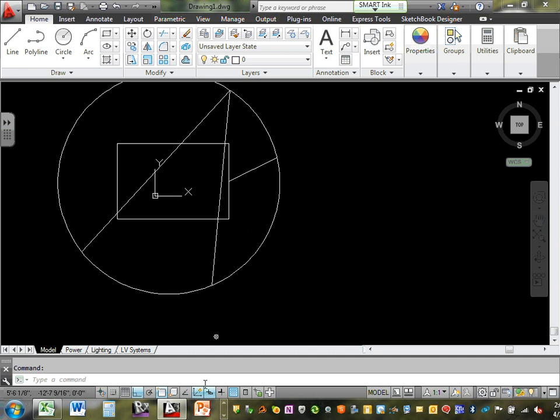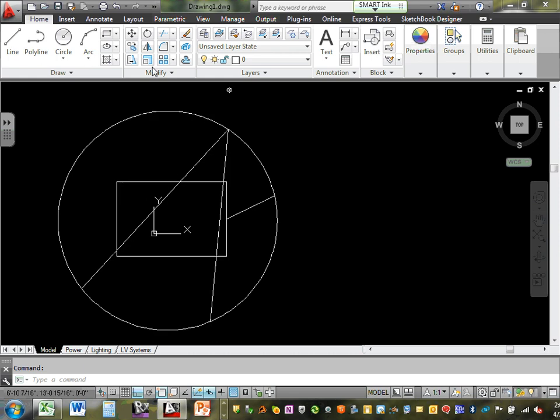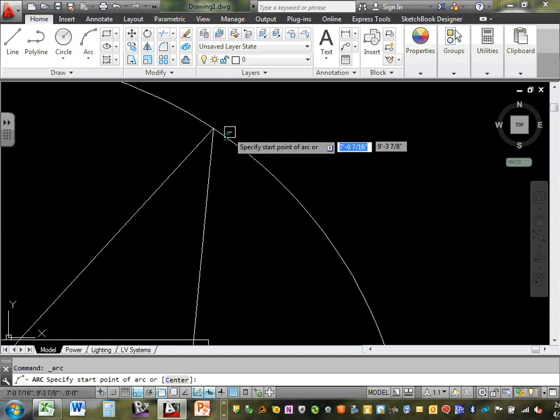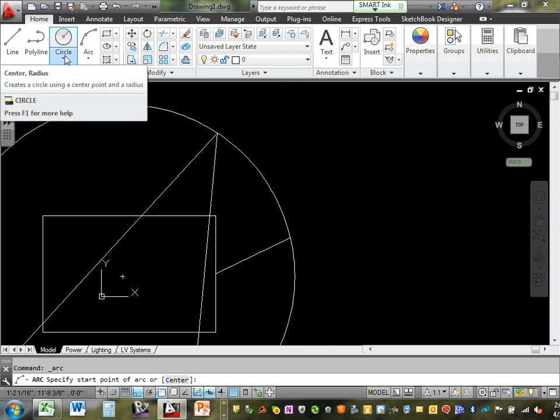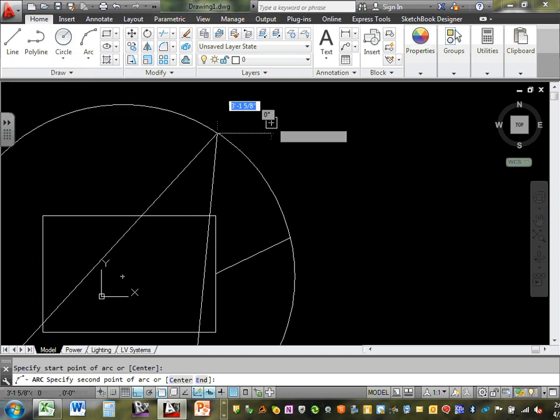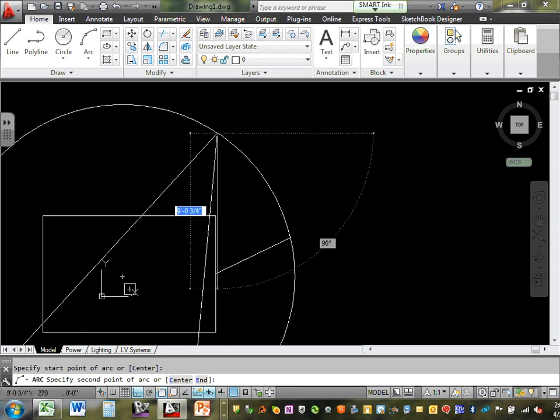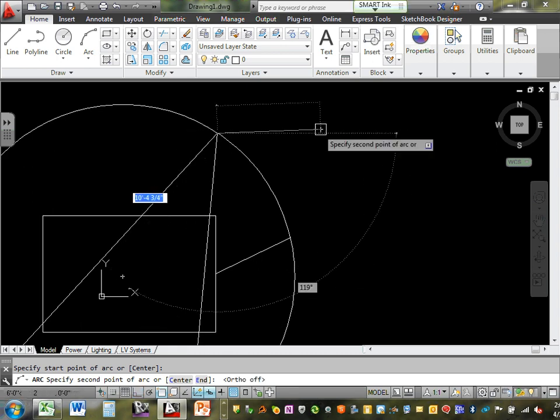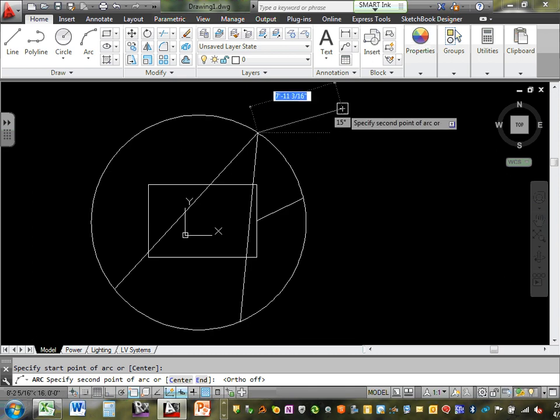Now, we know how to do orthogonal, right? We know how to snap, and we set our snap to object right here. So let's take a few things, guys, and we know how to draw. The arc is very powerful, guys; we use the arc all the time. Click on arc under draft right here. Then click the first button, and it tells you where you want the center of the arc. Oh, I'm in ortho. Because I'm on ortho, I can't make an arc. So you need to get yourself out of ortho, which is easy. Where's my ortho? Right here. Unortho yourself.